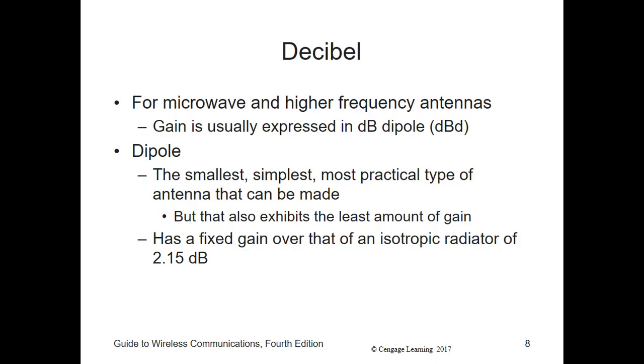Therefore, if you want to know the absolute power of a particular signal supplied by a transmitter, and you know from the specifications for this particular unit that the strength of the output signal is plus 36 dBm, you calculate the absolute power by breaking the number down. So you have 36 dBm, which is 10 dBm plus 10 dBm plus 10 dBm, because you want to use tens and threes, plus 3 dBm plus 3 dBm.